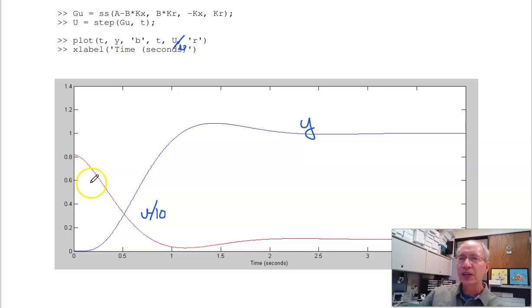So that is homework set number 5 for ECE 463 Modern Control, pole placement. The beauty of pole placement is you can put the poles anywhere you want. The weakness of pole placement is the dominant pole. You kind of know where that one belongs. That tells you the step response. All the other poles, it's really unclear where you should put them. But on paper, it doesn't matter. In practice, some places work better than others. What kind of worked here is if the open loop system is already fast, leave the poles alone. But that's homework set number 5 for 463.